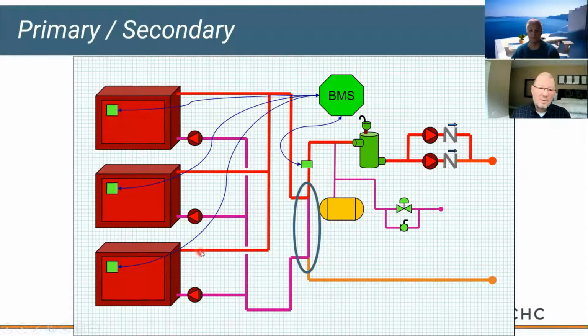What's also not shown here, typically leaving each boiler, you might have a balance valve. So you're going to balance the flow from each one of these pumps so that each boiler has the same flow rate, same delta T at high fire. Obviously, piping lengths could vary, but we're going to balance that in with some type of balance valve in the field. Now let's go over and look at polls.